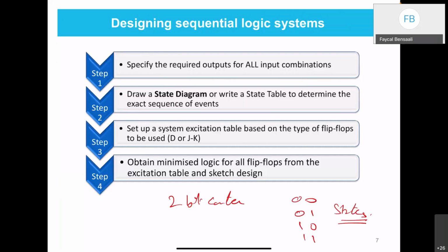So when you start designing the system, you should know what your states are. If you design a traffic light, how many outputs should you have? You should have 3, right? Because we have 3 lights. So 1 output for each light, controlled by each flip-flop. So you will have a circuit that has 3 outputs. 1 will go to each light, and then you control the lights.